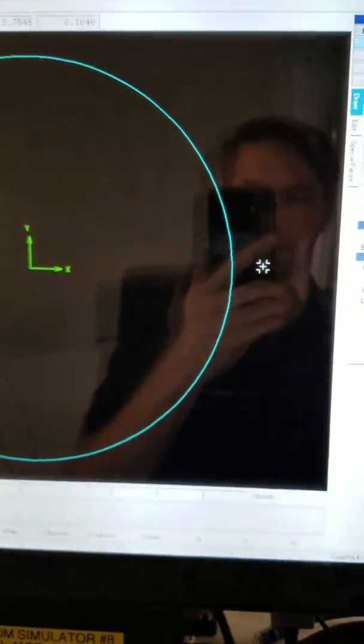So these are going to be your start points, where you want to start cutting into your hole. So let's say I'm going to have a start point here and out there. So my first start point is going to be at 5.25, comma 0. So we're going to start 1/4 inch outside of our circle. Then we're going to also start at negative 5.25, comma 0. And that's our second start point.